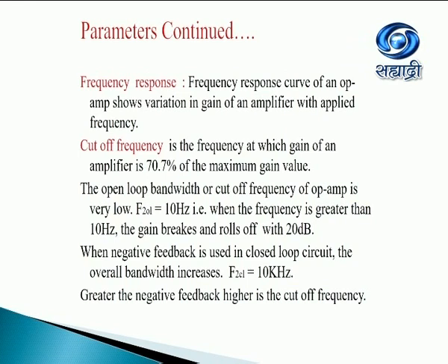Cutoff frequency. Cutoff frequency is the frequency at which gain of an amplifier is 70.7% of the maximum gain value. The open loop bandwidth or cutoff frequency of op-amp is very low. F2OL is 10 Hz. That is, when the frequency is greater than 10 Hz, the gain breaks and rolls off with